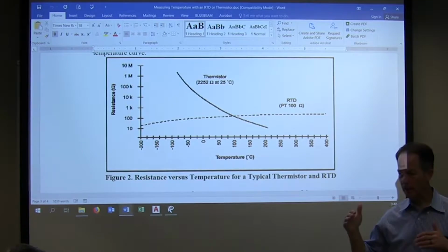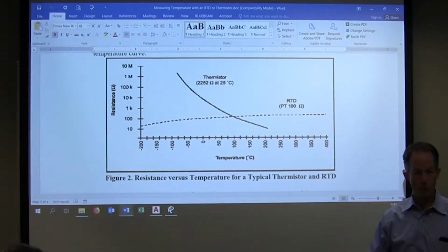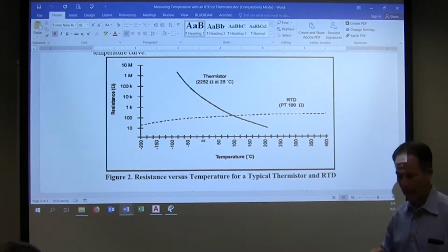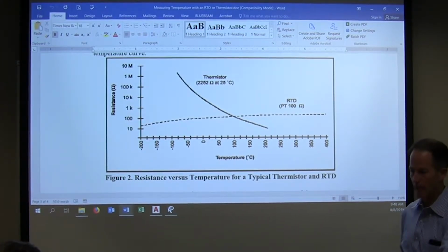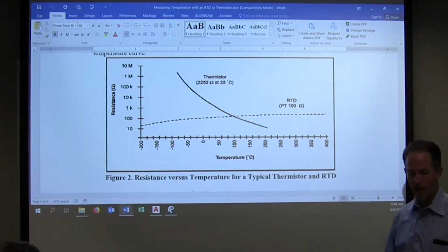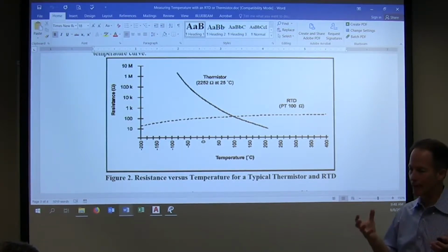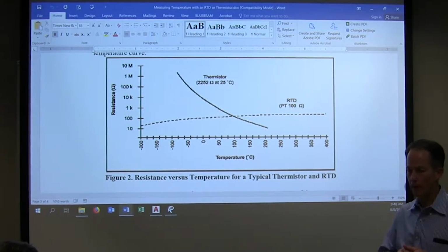Now, why am I picking 55? A lot of times we're around 55 degrees. So if I put a meter on something and I'm not remembering this chart, because it's not in my hip pocket and I didn't memorize it, but I read 16,000 ohms, 17,000 ohms, 18,000 ohms, it's kind of like a reality check, a sanity check. That seems in the ballpark, right?